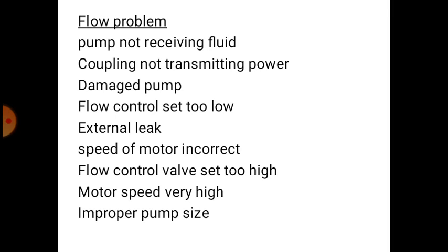Flow problems. Pump not receiving fluid, coupling not transmitting power, damaged pump, flow control set too low, external leakages, speed of motor incorrect, flow control valve set too high, motor speed very high, improper pump size. So these are the flow problems.